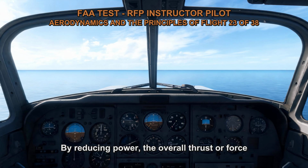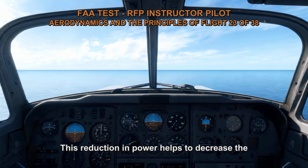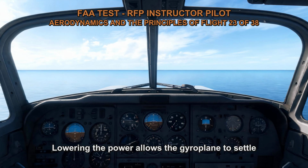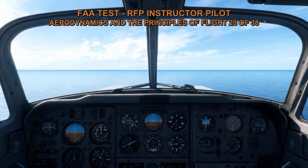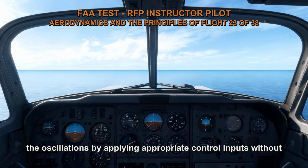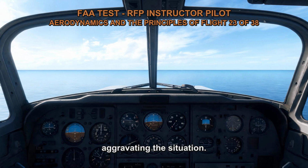By reducing power, the overall thrust or force being generated by the engine is decreased. This reduction in power helps to decrease the energy input into the system, making it easier for the pilot to regain control and stabilize the gyroplane. Lowering the power allows the gyroplane to settle and reduces the effects of excessive control inputs. It gives the pilot more opportunity to correct the oscillations by applying appropriate control inputs without aggravating the situation.